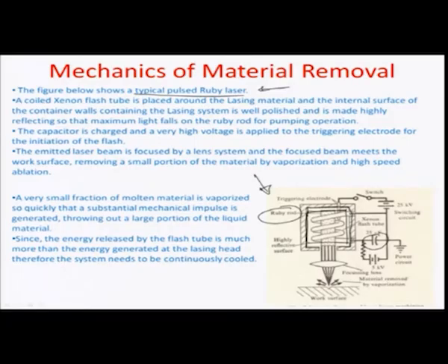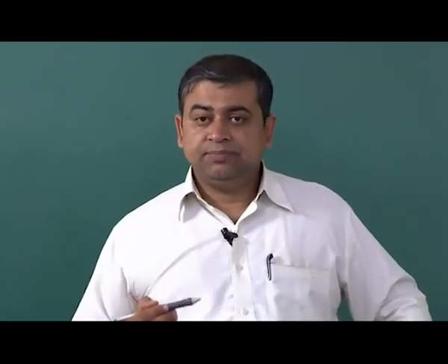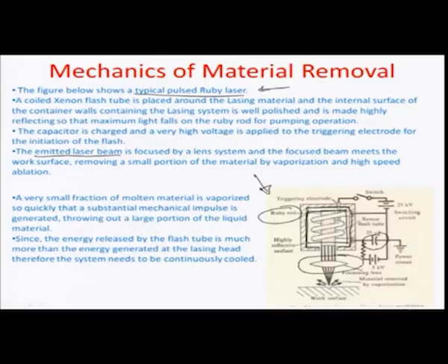The emitted laser beam is focused now, and of course there is this whole principle of amplification and emission happening, and there is occasionally a loss of photons. Most of the photons are retained within the medium for amplification, but occasionally photons are lost which form the cutting beam, and it comes out of the optical system, hits this lens right about here, and then gets focused very narrowly onto a small spot near the workpiece. So, you have to really focus a laser system with respect to the workpiece very closely before you start the melting and vaporization process.